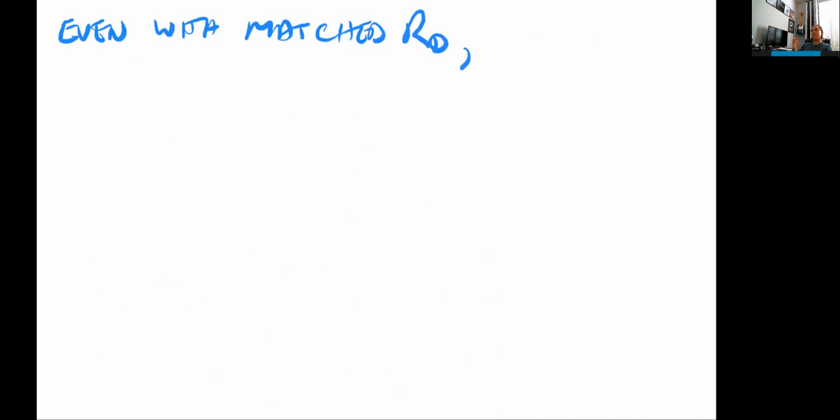So let's make a note for ourselves here that the equivalent of matching the RD is when you bias the transistor, making those current sources or current mirrors perfectly match themselves. Remember that we really don't have a resistor there. Those are biased networks.